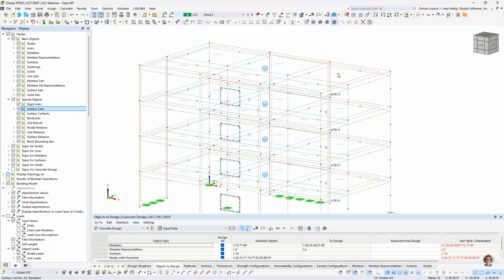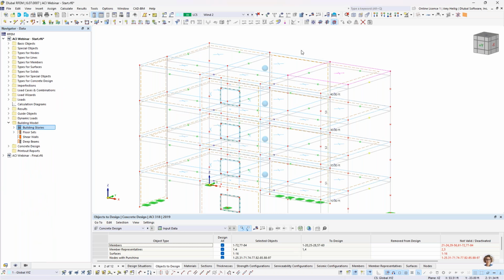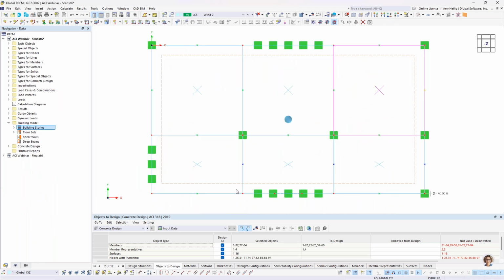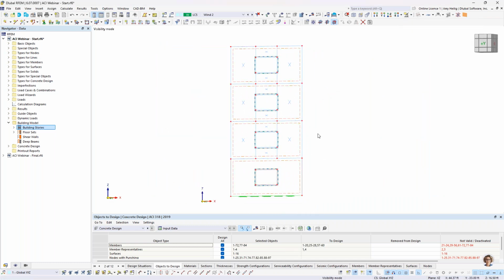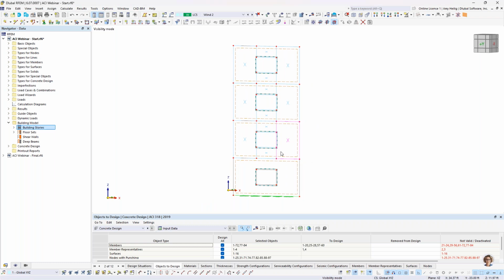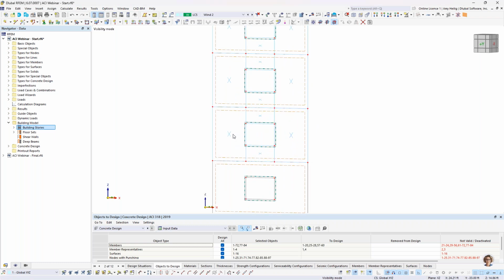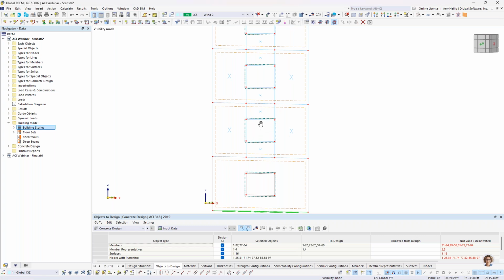And you can see here that it creates these surface cells at various portions of the structure on the surface elements themselves. Well, I'm going to turn this into an elevation view here, and I'll go ahead and highlight only my front shear wall. So here we have our 4 shear walls displayed graphically here, and you'll notice that those surface cells for the shear walls at the 2nd, 3rd, and 4th level are shown. And this is really helpful because this will help us define what is a shear wall on the left and right hand side versus what's a deep beam that's spanning in between these openings.